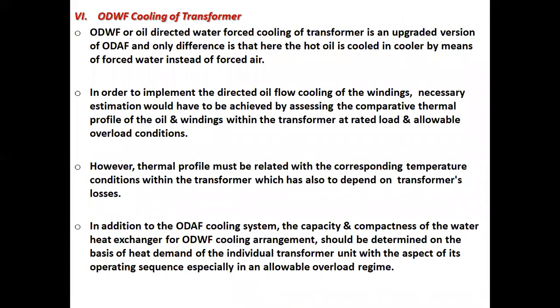ODWF cooling transformer. ODWF, oil directed water forced cooling of transformer, is an upgraded version of ODAF, and the only difference is that here the hot oil is cooled in the cooler by means of forced water instead of forced air.